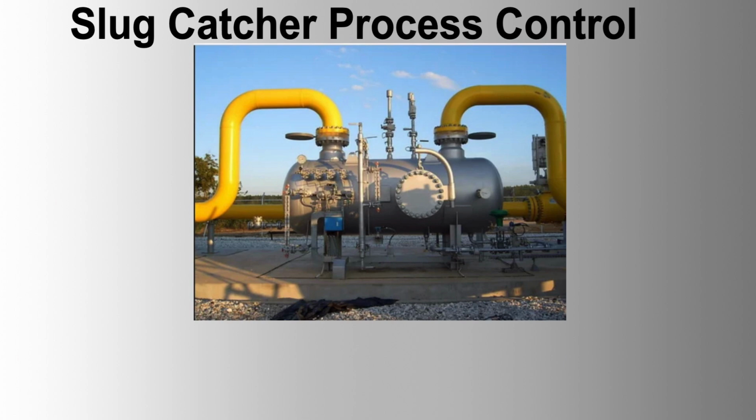Process description. 1. Inlet section. Function: receives the multiphase flow from multiple well clusters. Components: inlet manifold, flow lines, valves. 2. Separation section. Function: separates the incoming flow into gas, oil, and water phases. Components: separator vessels or finger-type slug catchers, demister pads, baffles.